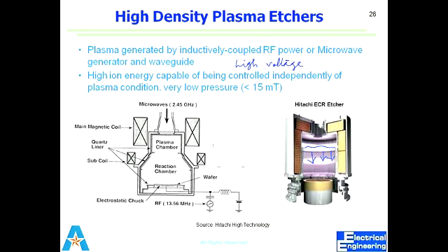So this method can be applied to wet etching process also, right? Yes, you're talking about wet chemical etching? Yeah, chemicals. In the wet chemical etching, I don't know what passivation layers you'll be using, and after that, how you remove only the passivation layer from the bottom. So usually we don't use that in wet chemical etching. Wet chemical etching is mostly considered as isotropic.